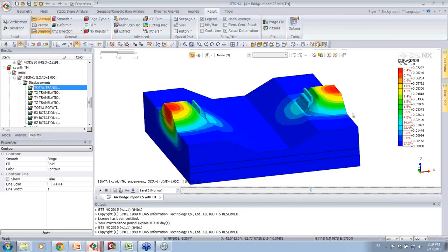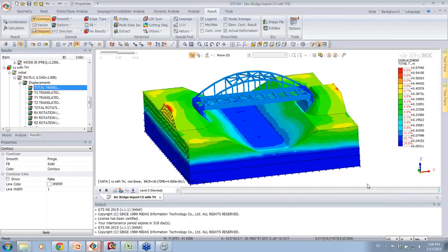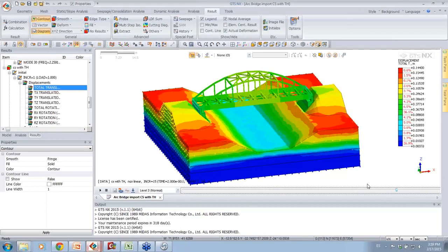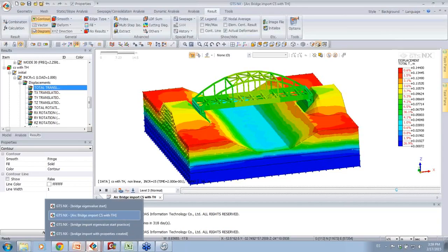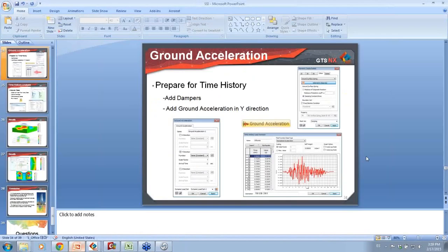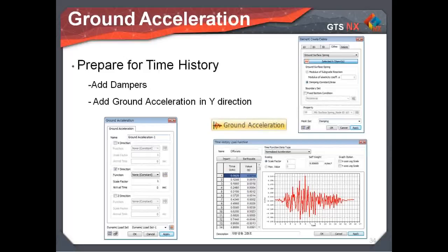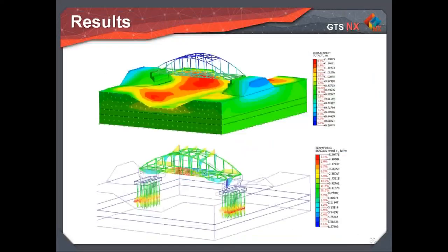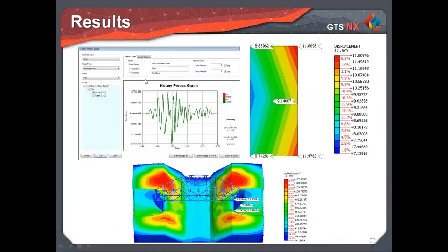Then we have the embankment created around it. Then we have the bridge. And lastly, we will have the other steps of the seismic function. So we can actually also do construction stages, keep those stresses from the construction stages, and then run a time history analysis. So I'm right at the time of the hour allotted. Basically, these are the steps that we just showed, the results, the bending moments. We can easily do them by points.